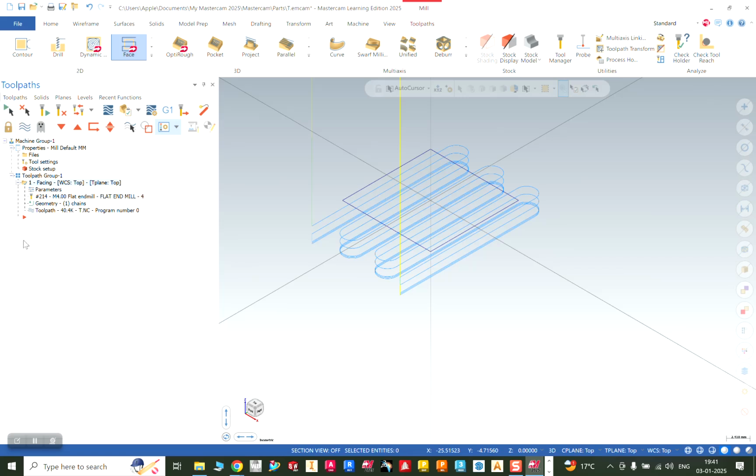So see, if you have multiple operations, it's only a face milling, it can be a spot face also, inside it we need to cut the material from inside. What is going to happen if you want to select all the operations at one time? You need to click on select all operations. The next one is select all dirty operations.